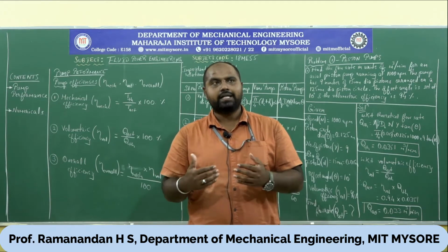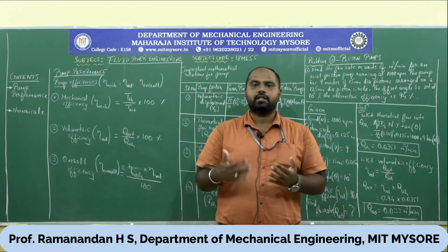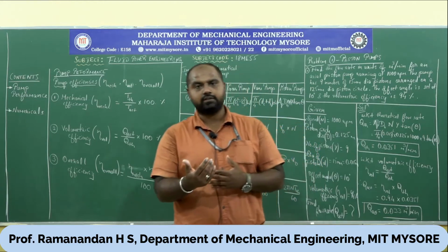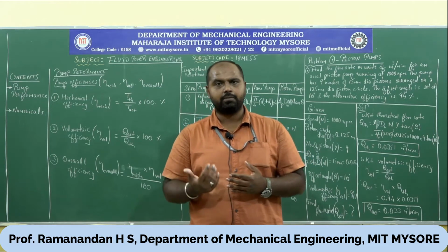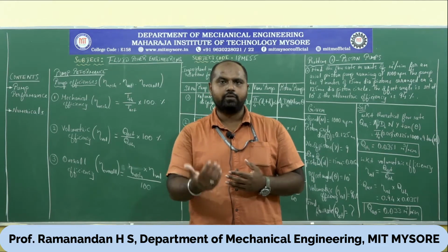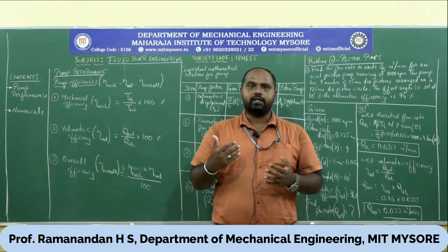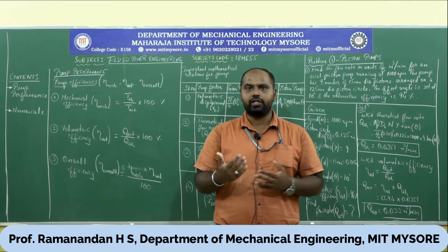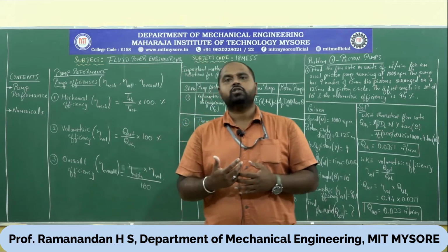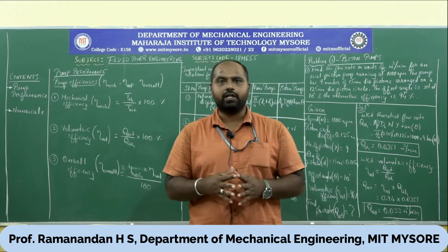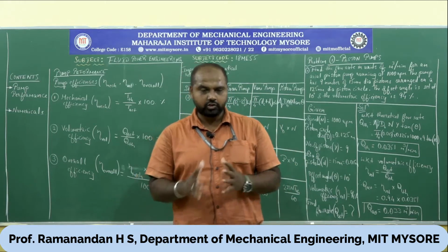So the pump creates flow. That is what we have seen. And pressure is just an effect of resistance between the moving elements, maybe pumping elements like gears or vanes or maybe pistons. Their movement with respect to each other, relative movement, will cause the resistance and the variation in the pressure. That is a result of suction and discharge. So that is just an effect of relative motion of the elements. The basic function of a pump is to create a flow. We are familiar with that now.